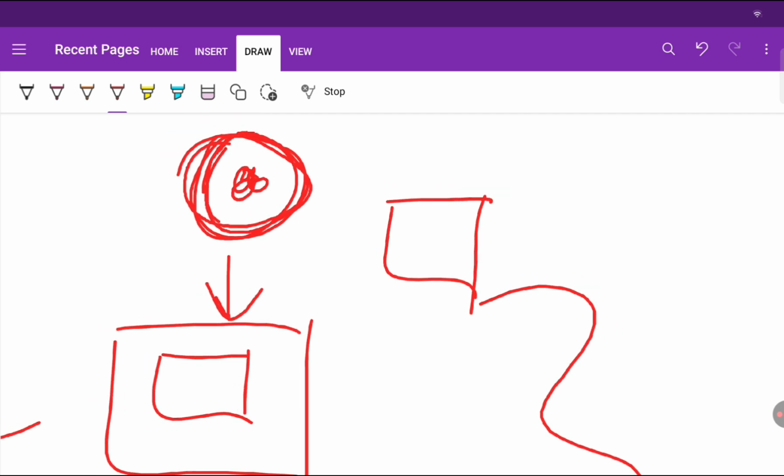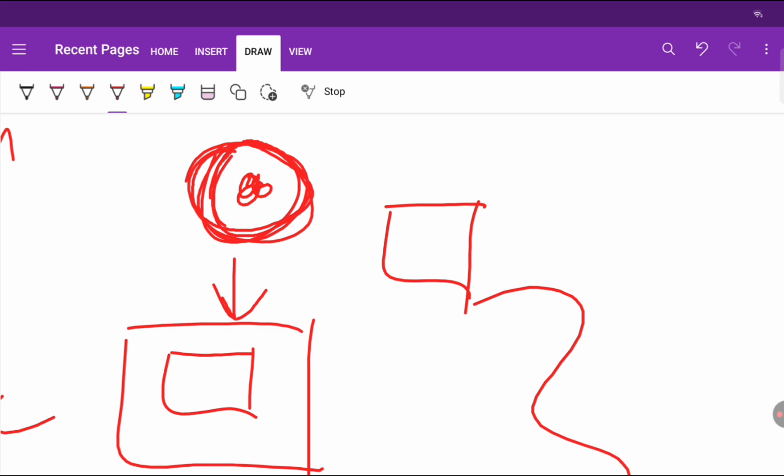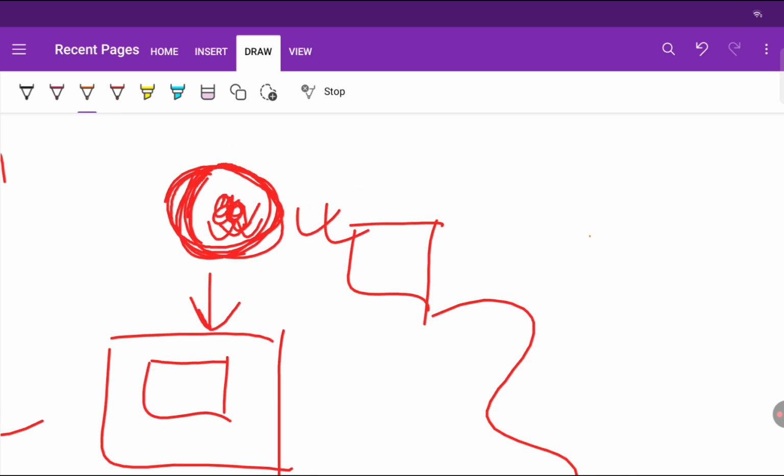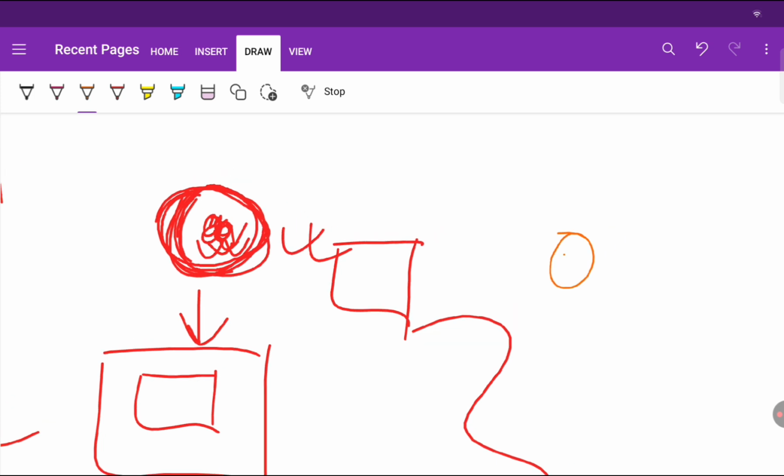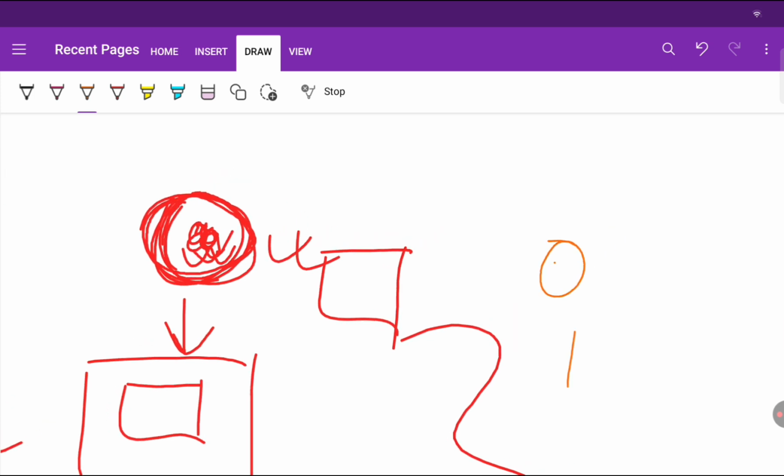At that time, this collar will not give any impression, but this annular ring will provide an impression. It will give just like a point impression. So till that time, it is considered as final setting time.